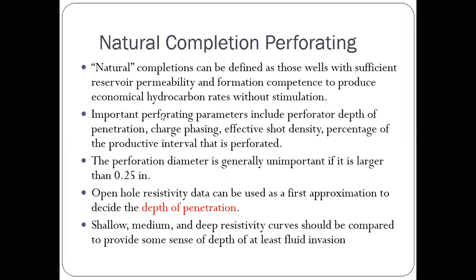So the important perforating parameters include perforator depth of penetration, charge phasing, effective shot density, and the percentage of the productive interval that is perforated. These are the important parameters which will affect the performance of the well. But if the diameter is generally more than 0.25 inch, then it is not of much importance. And as we discussed in the previous slide, it is important to decide the depth of penetration, and for that